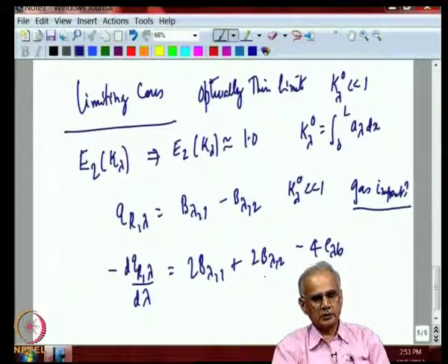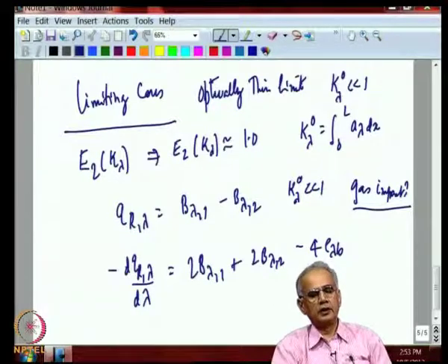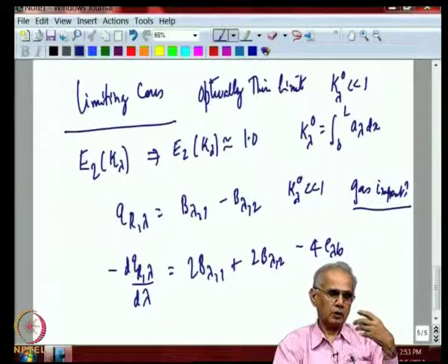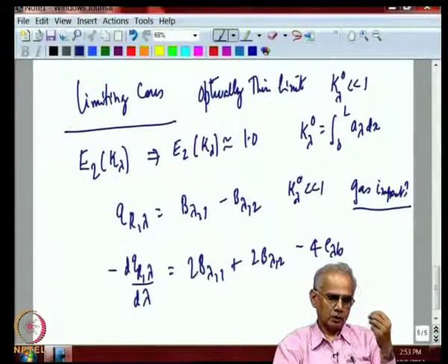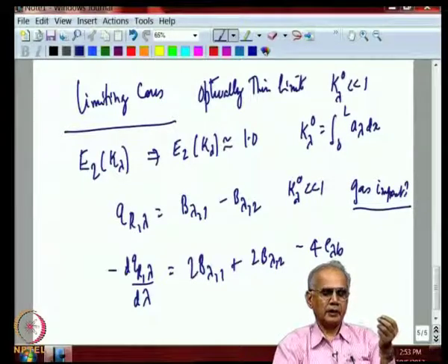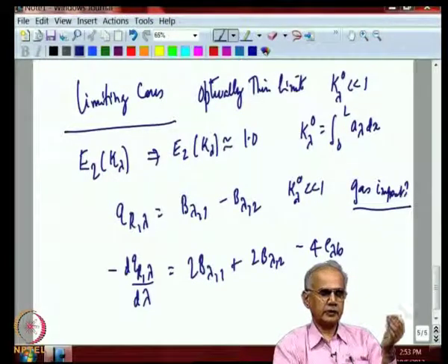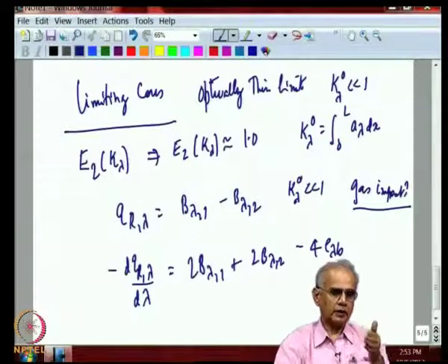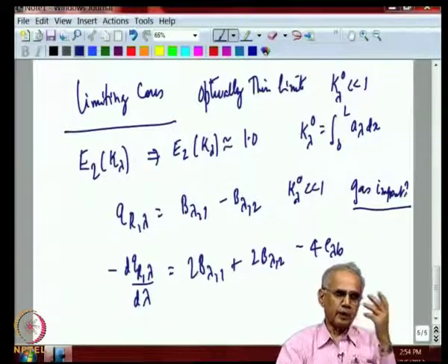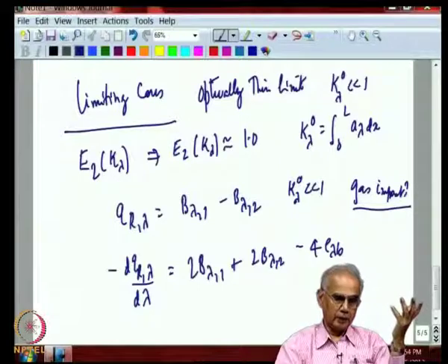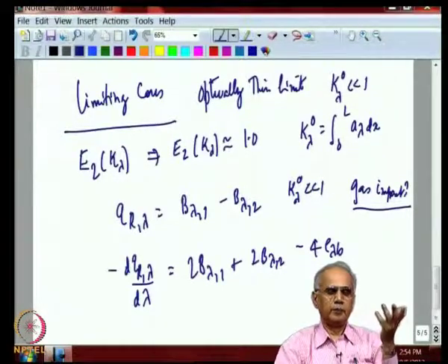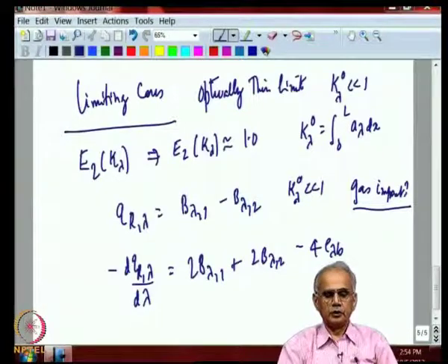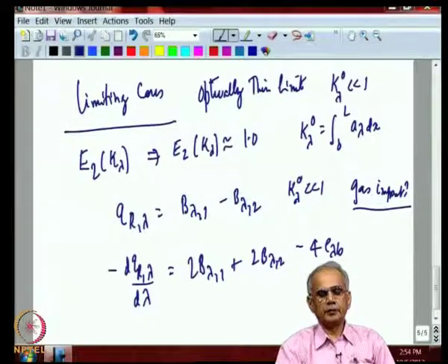The second one is absorption by the gas of radiation leaving surface 2, and what it shows is that in both cases the gas is so little absorbing that the intensity of radiation that comes to the layer kappa lambda is not affected by the passage through the medium, because the medium is very weakly absorbing. So, we have the absorption term and the emission term.